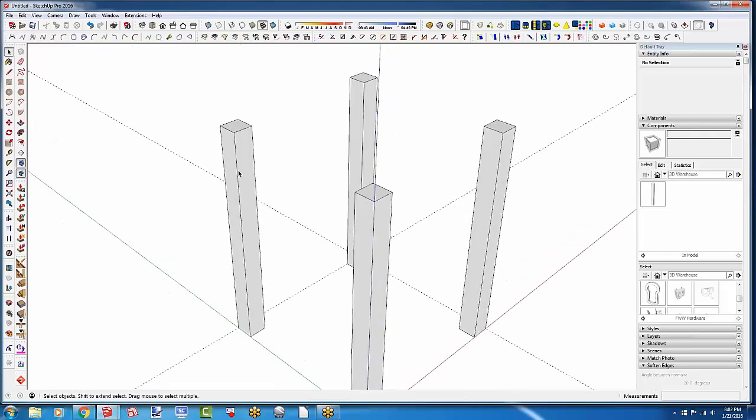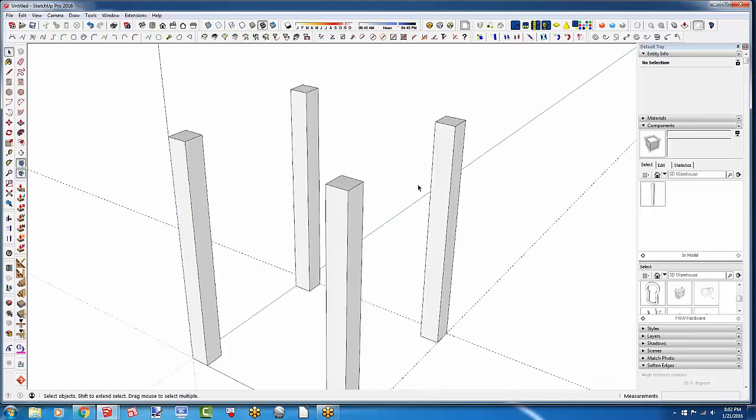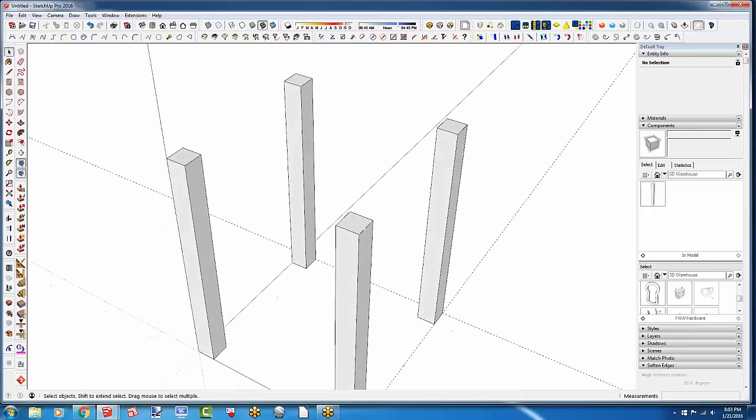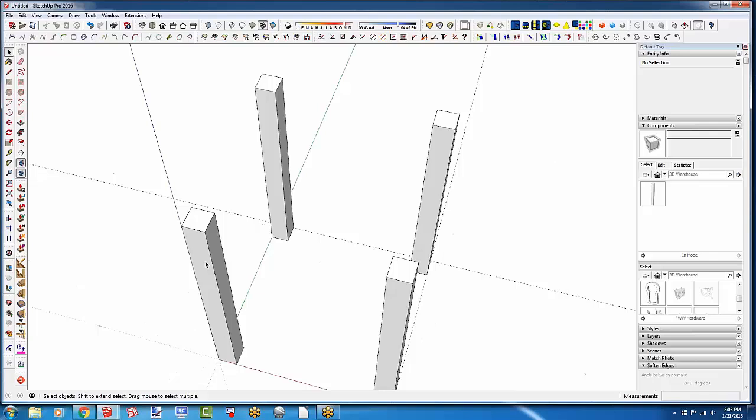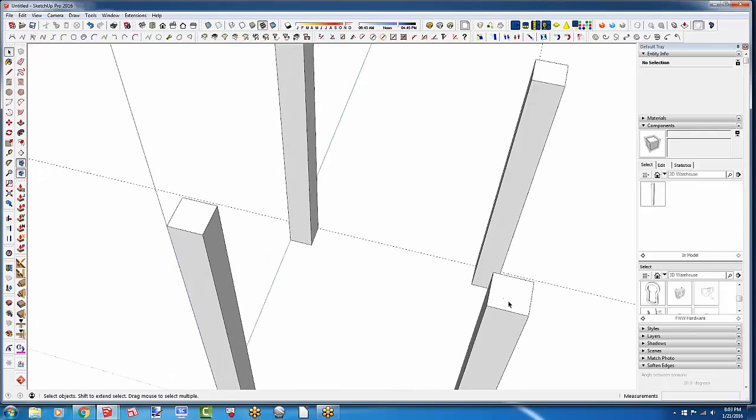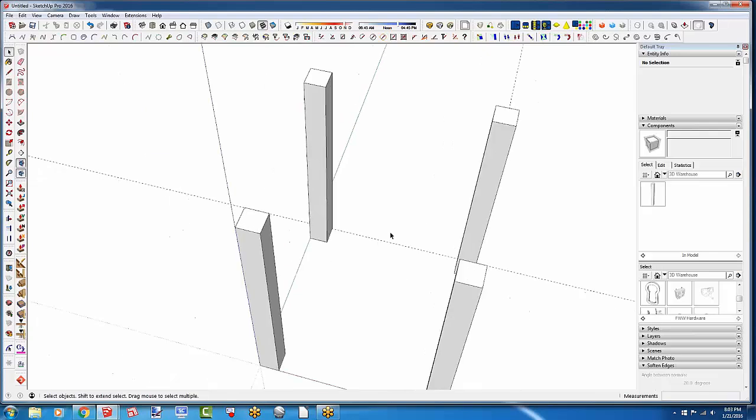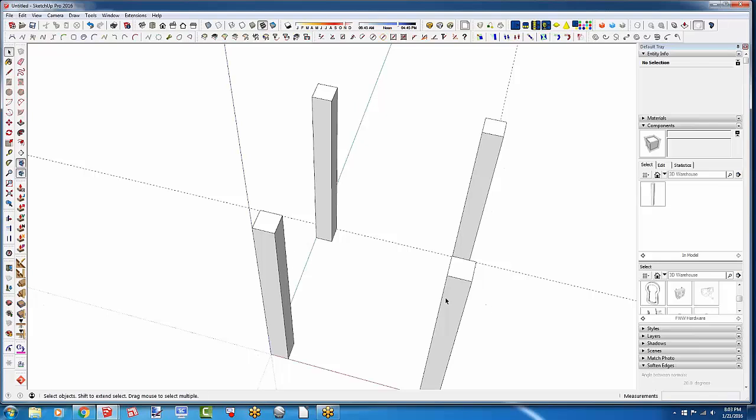Dave? Yes. You flipped that along the green direction. Why'd you do that? So I flipped the two back ones along the green direction. Thank you for stopping me on that. So they're mirrored relative to the front ones. And I had flipped the right one on the red direction. And so the flip direction is really the axis color between the components.